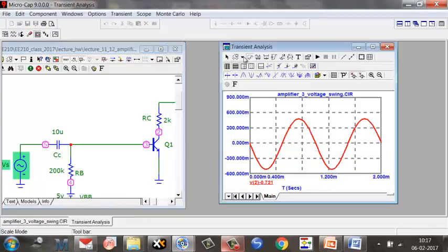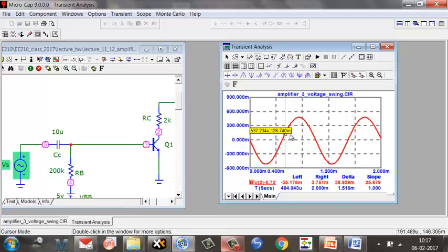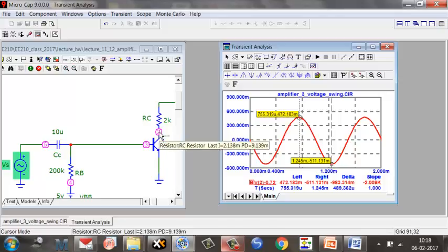All right, so what is the swing that I can get now? It looks like a reasonable swing of how much? 0.47 volts here. But interestingly, go here. Can you see something else happening? This is from node 2, I've subtracted the DC. Normally I may have a capacitor which will subtract the DC. So this is what I'm plotting.